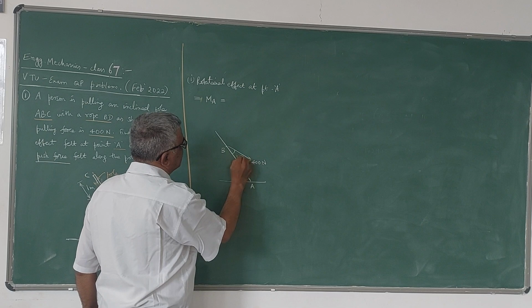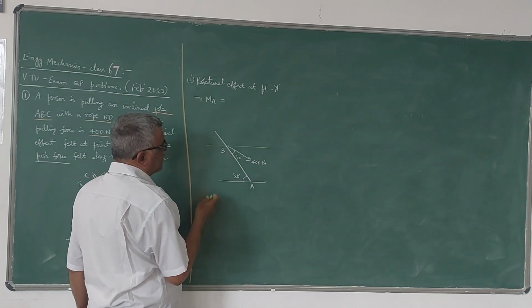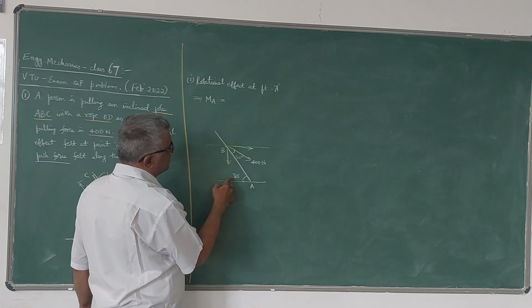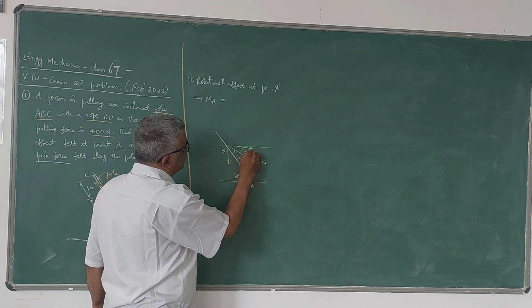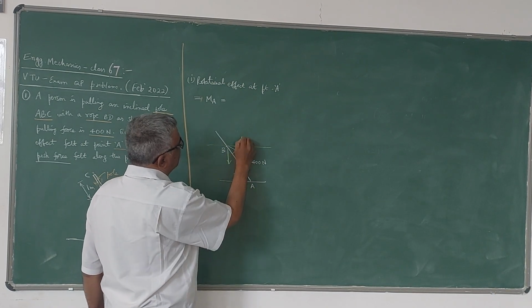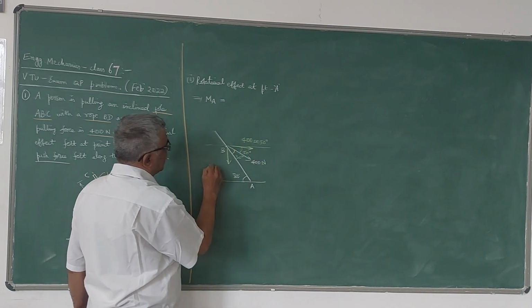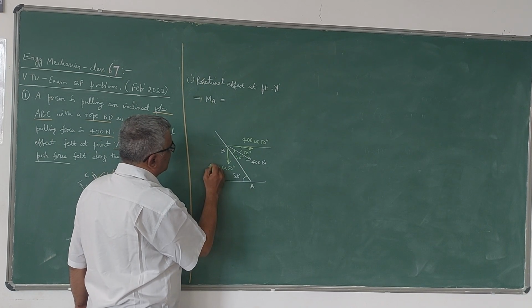30 degrees as given. So let me resolve this force into two components, horizontally and vertically. So like this. These are the two components. Since this is 80 degrees, this total will be 80 degrees. Therefore, this will be 50 degrees. So this force becomes now 400 cos 50, because that is the adjacent angle, and this is 400 sin 50.